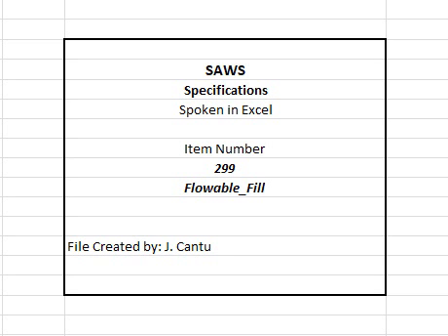4. Fine aggregate. Provide fine aggregate that will stay in suspension in the mortar to the extent required for proper flow and that meets the gradation requirements of Table 1. Test fine aggregate gradation in accordance with TxDOT Standard Laboratory Test Procedure TEX 401A. Plasticity Index, PI, must not exceed 6 when tested in accordance with TxDOT Standard Laboratory Test Procedure TEX 106A. 5. Mixing water. Use mixing water conforming to the requirements of specification item number 300, concrete, natural aggregate.